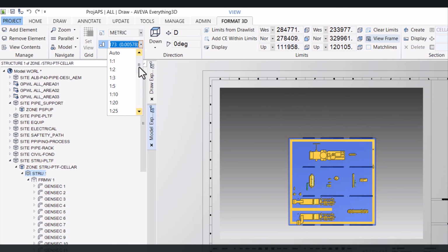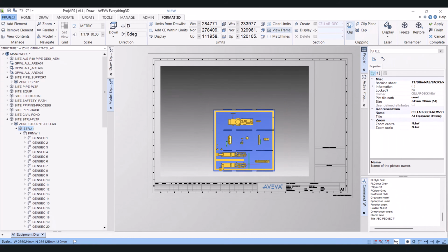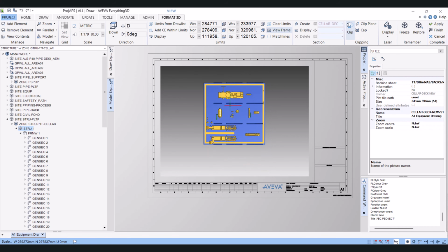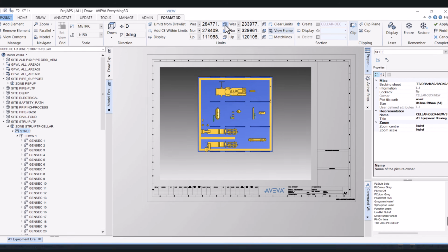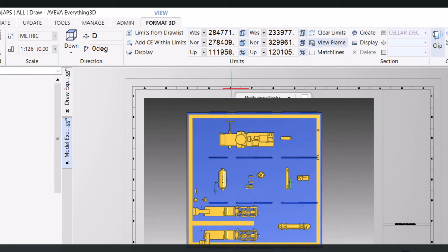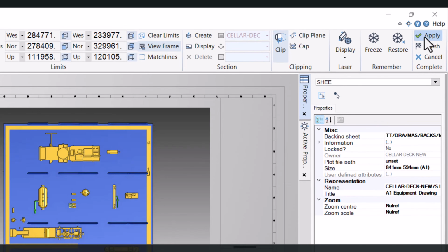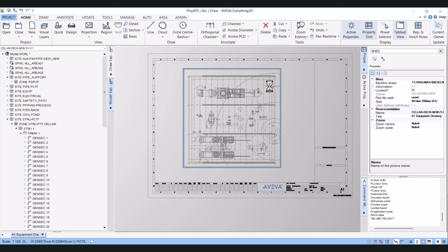and you can select the scale here, and we'll select 1:50. One is to 150 here, and now we have to click these boxes to fix the limits. All done here. Now we have to click here on apply. This one, tick, apply. Now your view is generated.